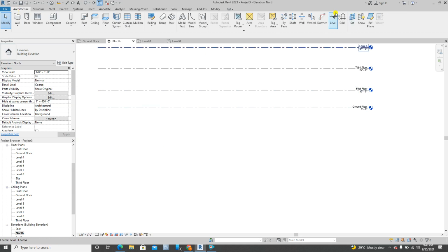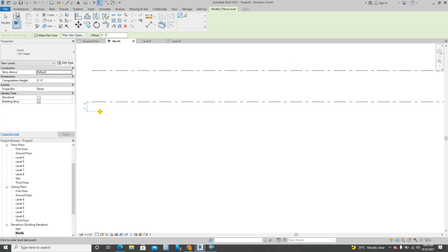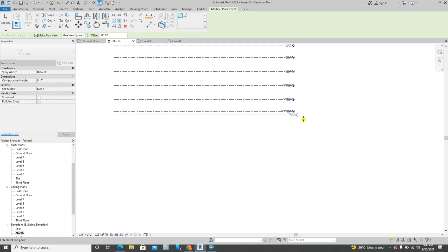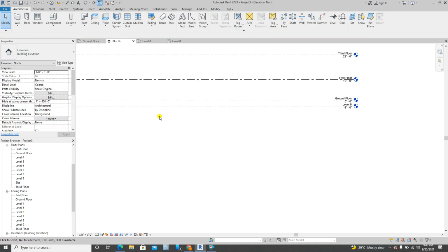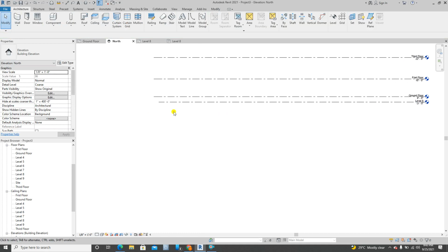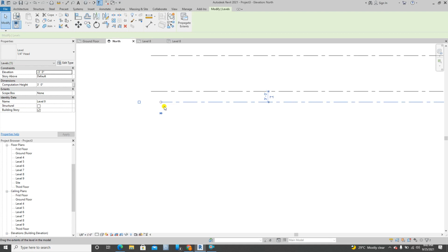I'm going to go architecture, level. I'm going to make that a plan view. I'm going to go minus 3 feet, and I snap into this. Okay, so you notice I did something wrong. I purposely did that.